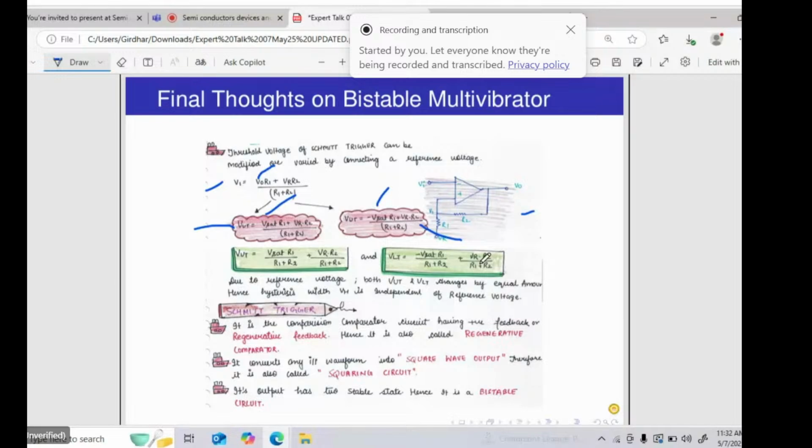Right. Now let us come to a problem on the bistable multivibrator. Here I have given a bistable multivibrator based on this circuit. This voltage is the reference voltage 4 volts, and this is the output voltage. This is Vi, this is V1. Now you have to plot the hysteresis loop and calculate the hysteresis width, and this is your target here. What should be the approach?